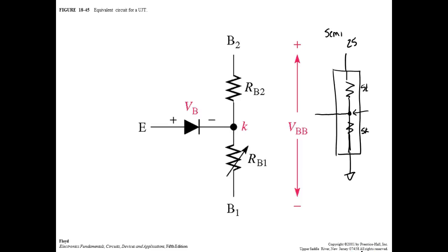I've got 25 volts applied to the circuit, so they've got to drop the same voltage, and Kirchhoff's law says all the voltage has to be dropped. What's this resistor right here going to drop? Good, 12.5 volts. So this one right here would be what? 12.5 volts. Okay, you understand?